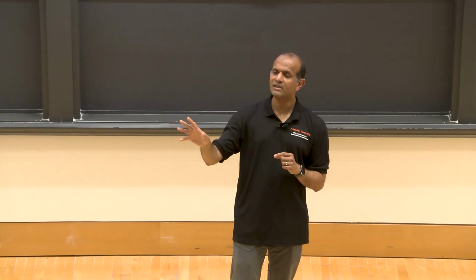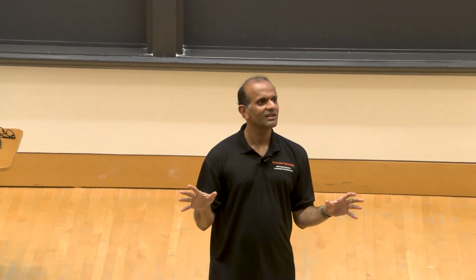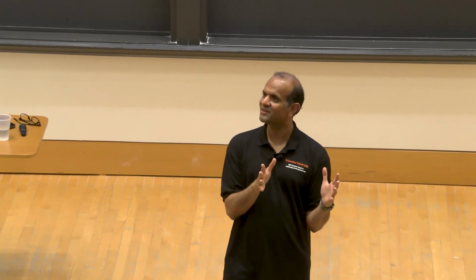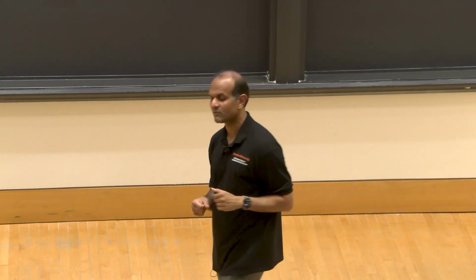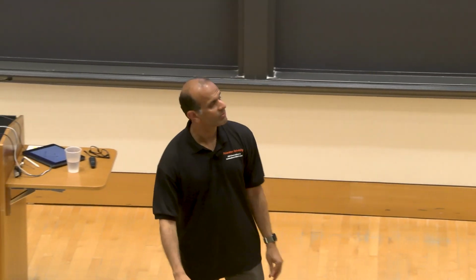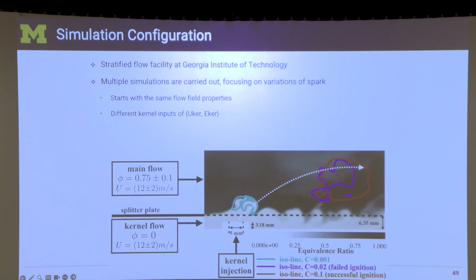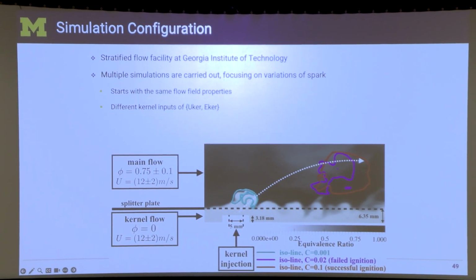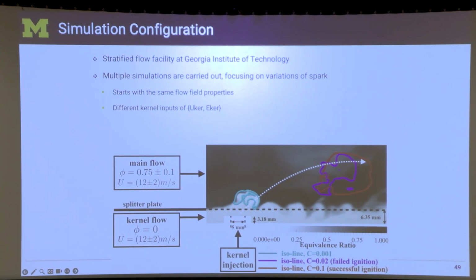Something you do not want in any engineered system, certainly not in an aircraft engine, right? You press a button, it should work. You don't want it to say, no, today I'm not going to work. Yeah? So this is a very dangerous thing. So what you're trying to figure out is reducing this variability. How can you reduce the variability? Now, there's a very simple way to reduce variability. That plasma torch that injects that high temperature fluid, you just put a gigantic plasma torch so that it just sends in enormous amount of hot fluid. If it does it, it will always burn, no questions asked. But the power required to make the discharge will be so high, you need additional backup for that. Right? So it's not going to work in regular place.